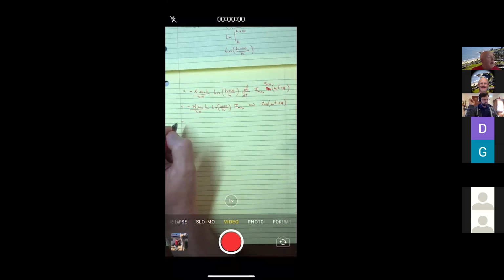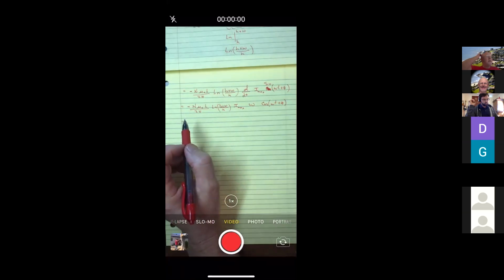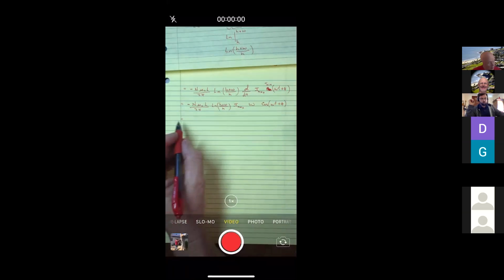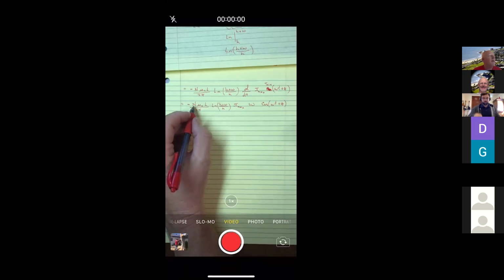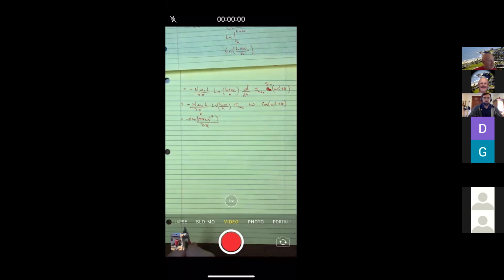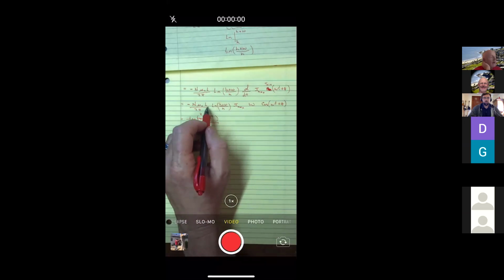And so now they gave me all these parameters. Let's see, determine the induced EMF. So n is 100. Mu naught is 4 pi times 10 to the negative 7. But again, I've got a 2 pi downstairs, so I'll just cancel to save a couple keystrokes on my calculator there.